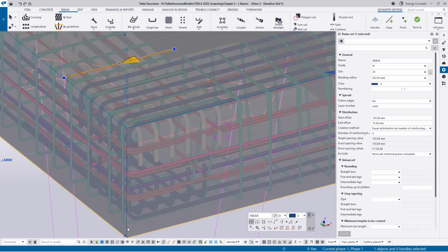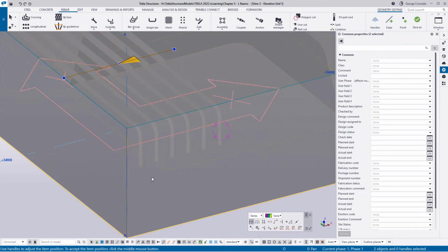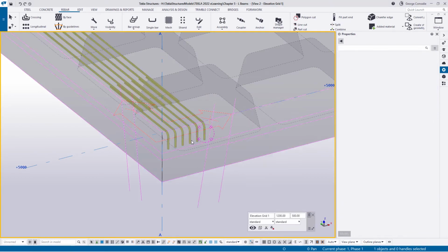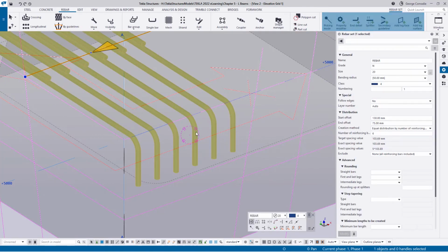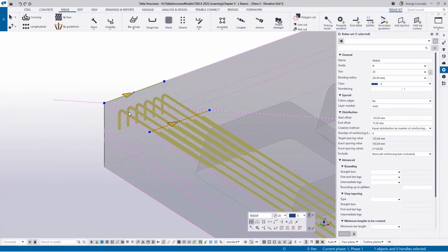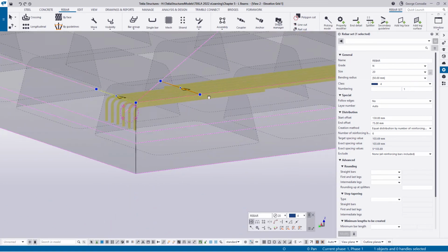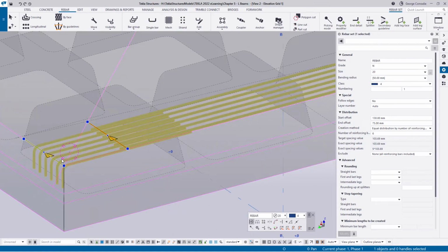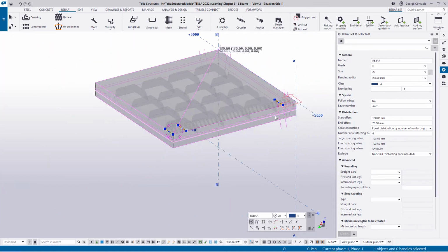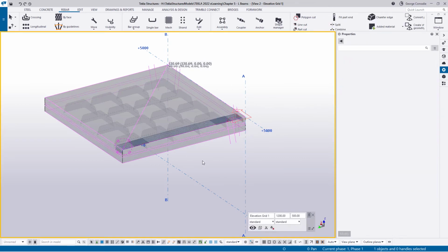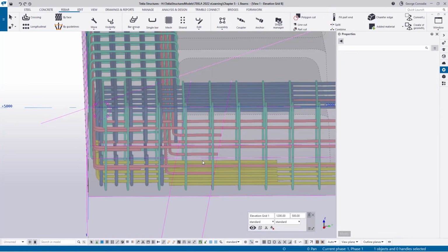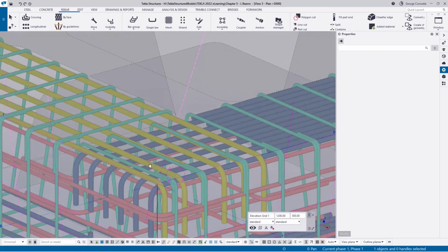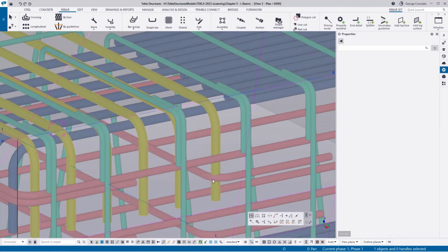and the concrete. Right click, show only selected. And then what I'm going to do is trigger my construction lines again so I can see this sort of thing. So if you click here, if we go to the opposite side, we've got a guideline here. Now I've got my view not set deep enough. So let's go over to the 3D view so we can see it better here. I just have to find the bars again. So these bars are clashing with that.